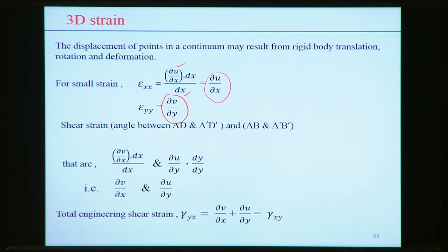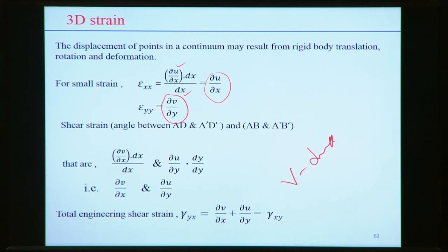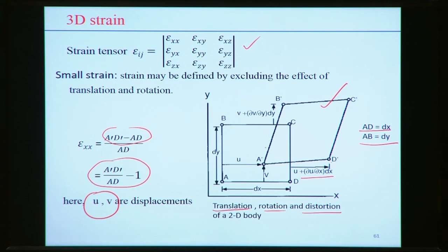Now when you try to represent the strain as shear strain, basically in terms of the angular form, in the small distortion case the shear strain can be approximated simply by the angle. So here the shear strain actually represents this part, the total angular form here.